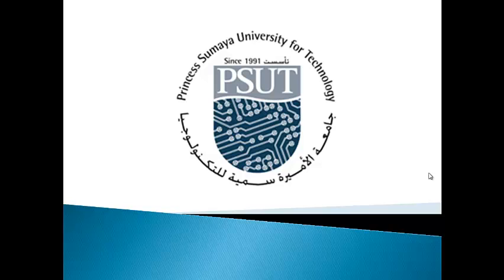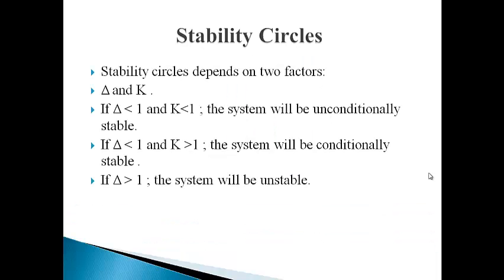We are going to solve a problem about stability circles and constant gain circles. Stability circles depend on two factors, delta and k. If delta is less than 1 and k is less than 1, the system will be unconditionally stable. If delta is less than 1 and k is greater than 1, the system will be conditionally stable. If delta is greater than 1, the system will be unstable.